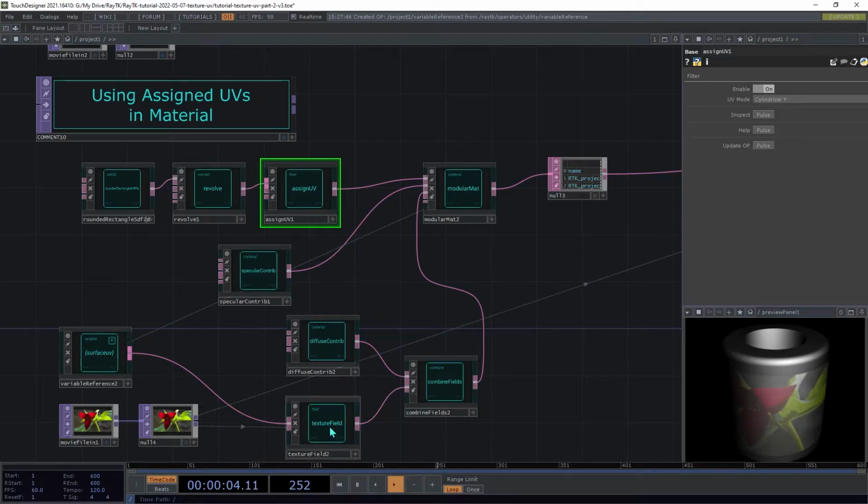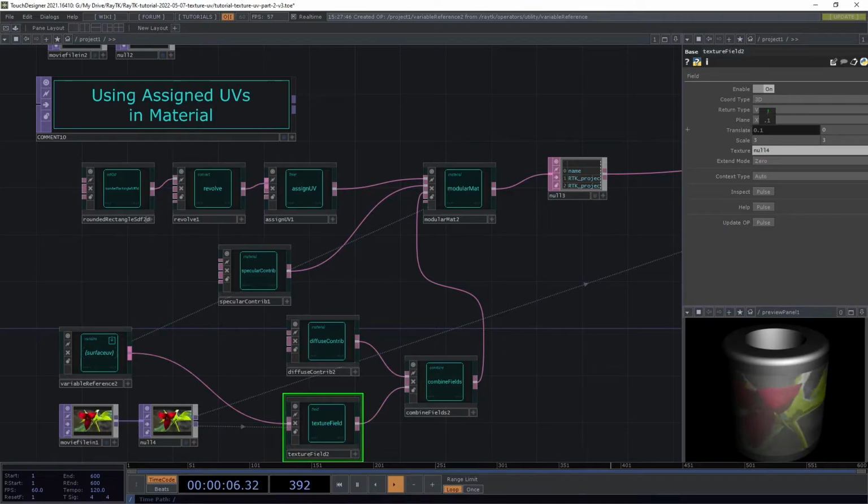And now if you adjust the translate on the texture, you'll notice how it's kind of wrapping around the surface, and you can see it a little bit there in the back when it wraps around. So in order to get this texture to fill the space, even outside the 0 to 1 coordinate range, we're going to set the extend mode to mirror. You can also use repeat if you want, and that will fill out all of the different places that the texture is used.